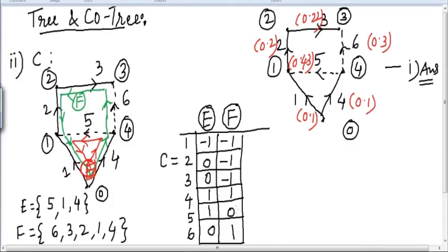Okay. Is it clear everyone how we have written the basic loop incidence matrix C? Once we write this basic loop incidence matrix C, we have to make a partition of this, and the partition is always made with reference to the branches and the links. So here the partition can be made in this way: the upper portion is branches and the lower portion is links. Why do we require this? Because you can see in the fourth bit they have asked you CB is equal to minus BL transpose. Anyways, we will require this. That's why we are writing here CB.